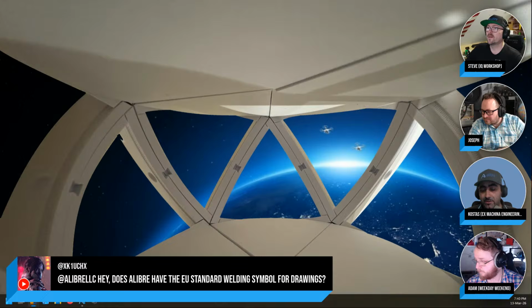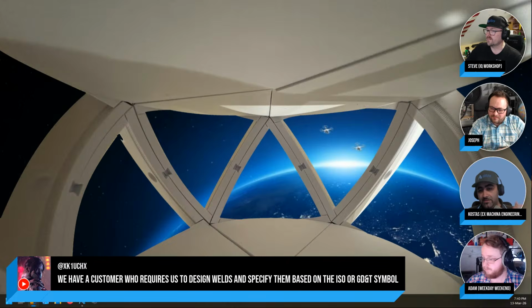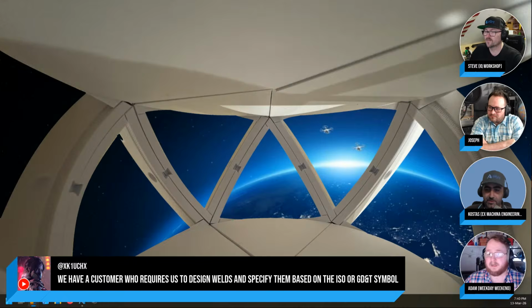And you need to know that, because if you design differently, and they might even give you K factors, if you design that differently, you might have small differences in dimensions in the final part. So, yeah, top tip there by Steve. Before you design, get in touch with your manufacturer, ask him how he wants things done.